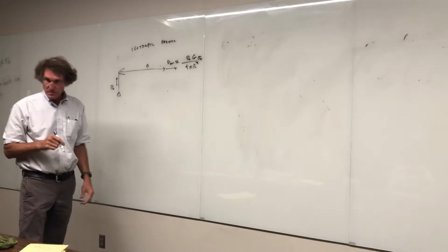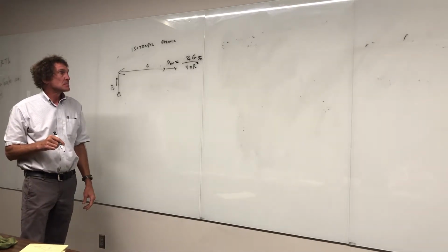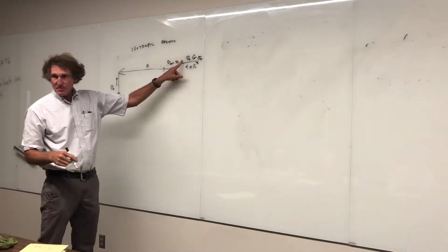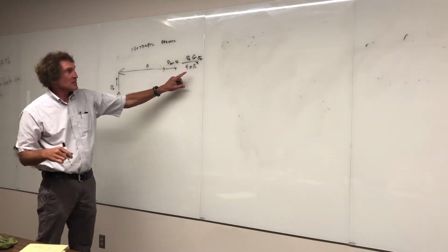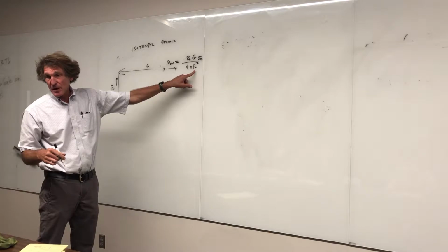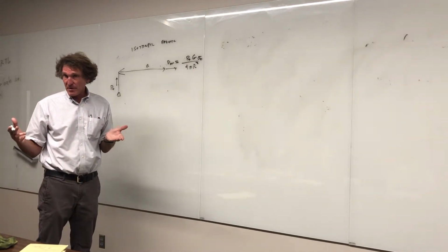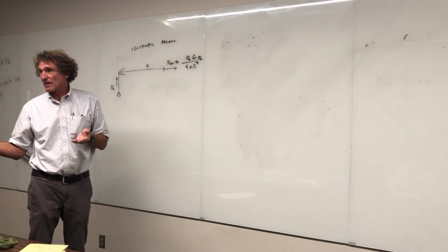Yes? That coefficient on the top, P average equals something times the G, replace that? This is transmitted power. Okay. This is, why don't I do an example? R is just in meters squared, how far away you are. And G is gain, it's unitless. It tells you how much better it is. I'll give you a simple example so it'll drive this home.